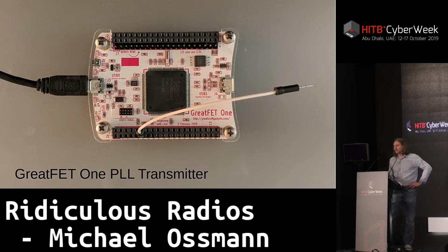The amplitude doesn't change, but the frequency is modulated, and that carries digital information. So it's a little bit different than what Mike Walters had done, and we were playing with the PLL, which is the clock generator in the GreatFET's microcontroller. And what we determined was that we could actually use two PLLs, one to generate each frequency of our frequency shift keying, the high deviation and the low frequency deviation, and then switch back and forth between them in real time to generate a signal.